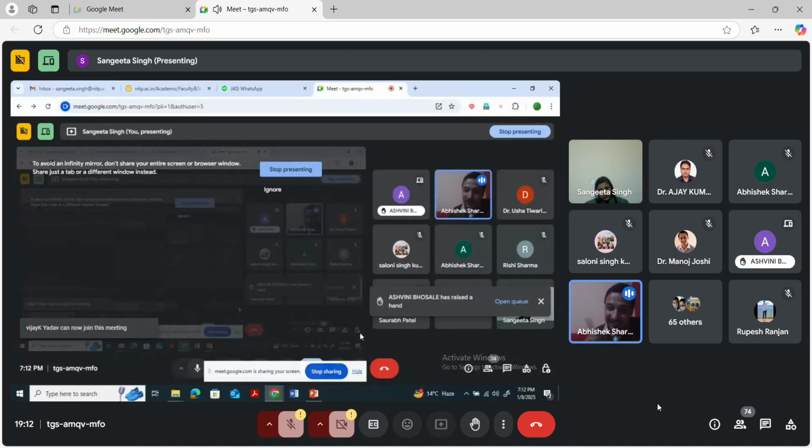Okay, the next question was the same which you have answered. Is any one of them being used practically nowadays in devices? Yes, negative capacitance FET, NC FET. Because it is symmetric, you only need two additional steps, one is a ferroelectric layer and another is metal. So NCFET is being used practically in devices.